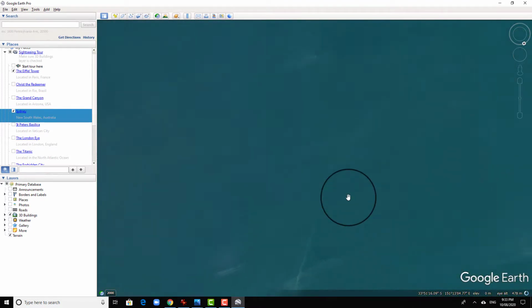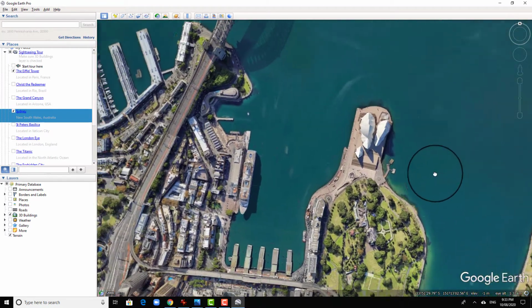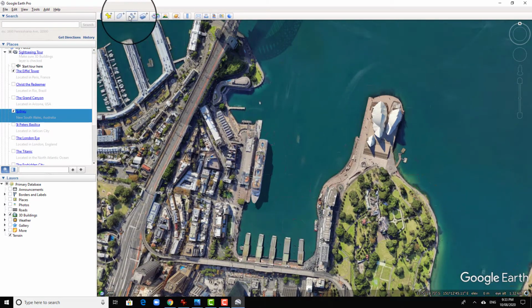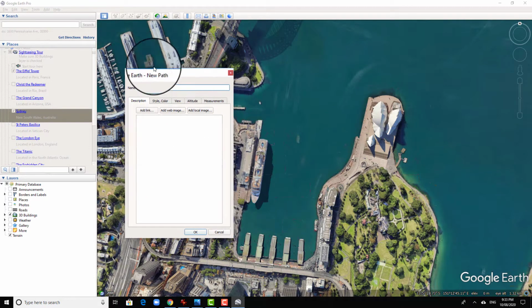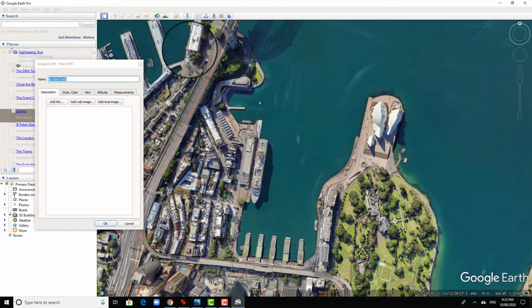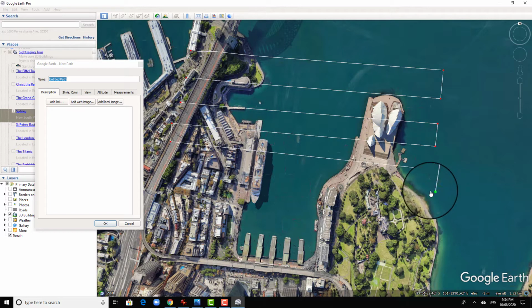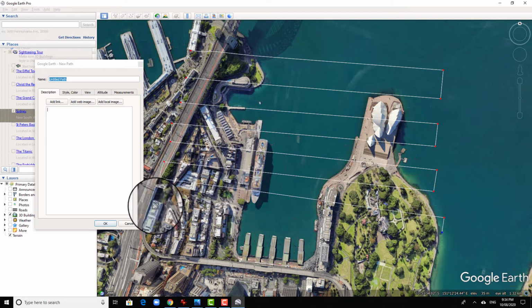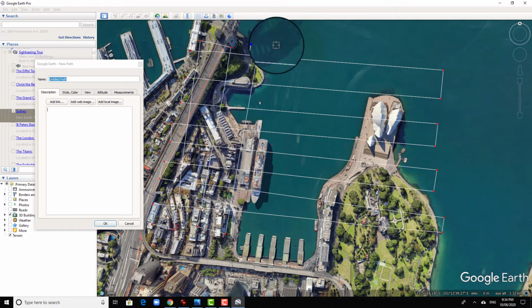We need to draw camera paths for our flying cameras by using this Add Path tool. We need to use a continuous polyline to form a grid. Our camera will follow this polyline and capture every perspective of this area. And the grid should be relatively small to make sure the camera can capture all of the area.